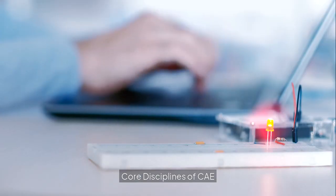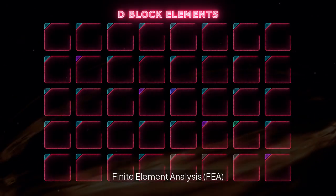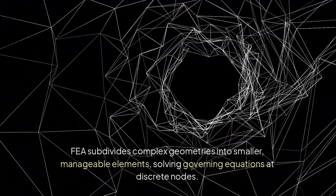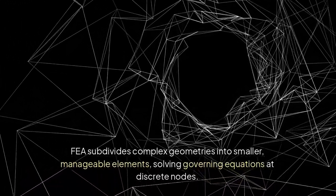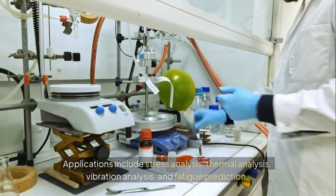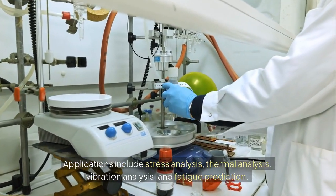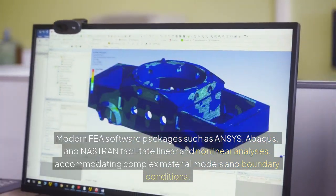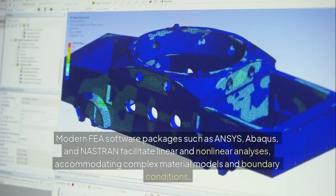Core disciplines of CAE: finite element analysis, FEA. FEA subdivides complex geometries into smaller, manageable elements, solving governing equations at discrete nodes. Applications include stress analysis, thermal analysis, vibration analysis, and fatigue prediction. Modern FEA software packages such as ANSYS, Abaqus, and Nastran facilitate linear and nonlinear analyses, accommodating complex material models and boundary conditions.